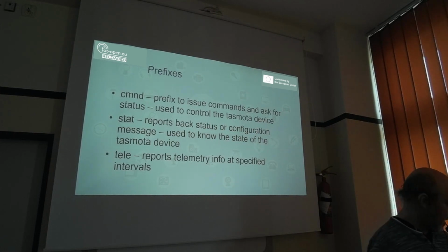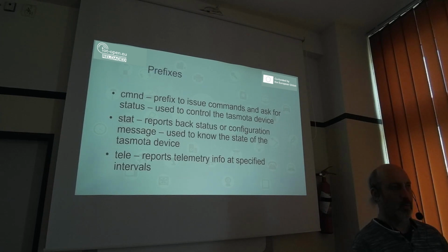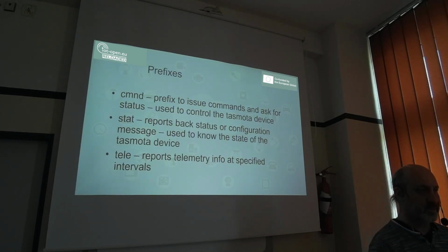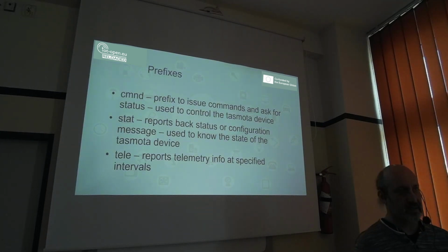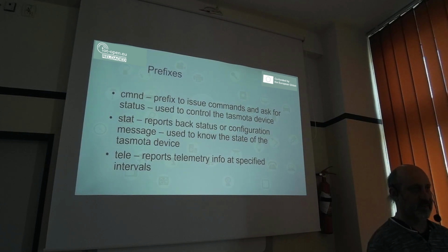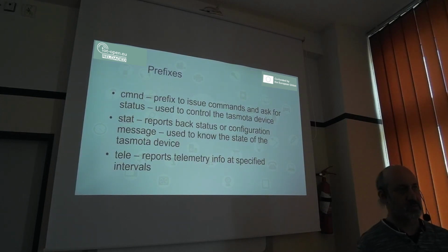Prefixes. CMND means command. This is the prefix that is used while we publish the message to control our device. So for example, if we want to switch our LED on or off, we will send a command. Next we have stat. Stat is the report, so we can say something like status. It is a report or configuration message used to know the state of the Tasmota device. So this is, we can say, a report from Tasmota.